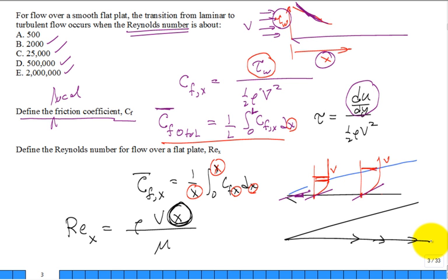You may have a finite length plate, and over the entire length of the plate, the Reynolds number starts at 0 and maybe only goes to 200,000. Guess what? It's going to be laminar the whole way. You may have another plate. It goes from 0 to 20 million. Well, where did it turn turbulent? Well, at 500,000, which would probably be like right over here. Because it's linear, see? So if it's 20 million at the trailing edge, at the leading edge, it's 0. It's linear with respect to the distance between the leading and trailing edge. So this would probably be where it's 500,000.